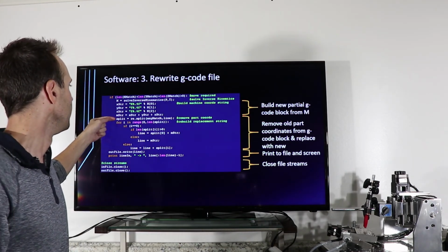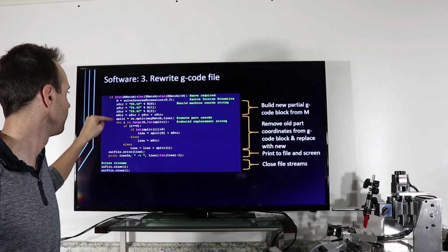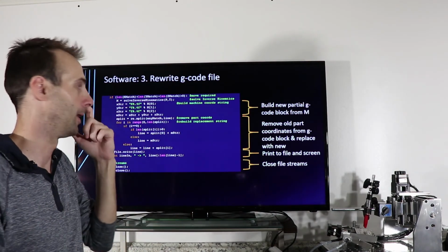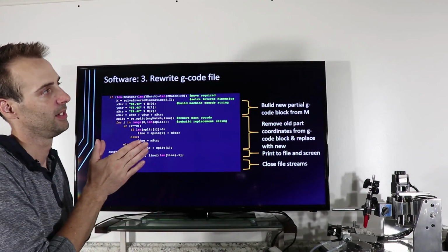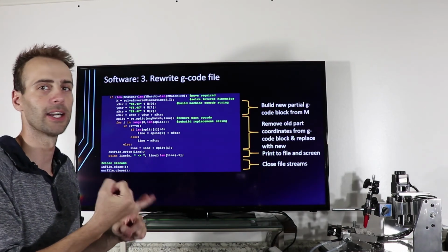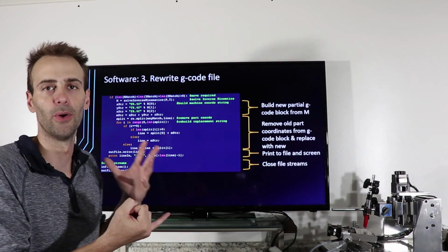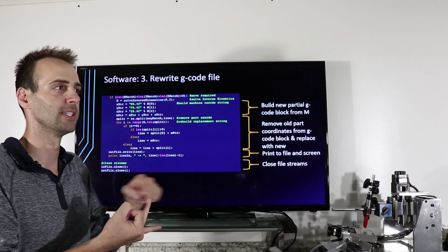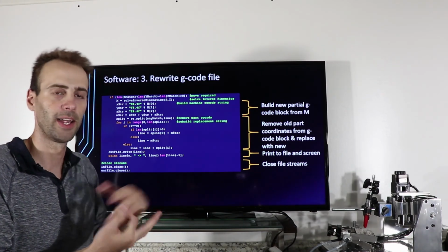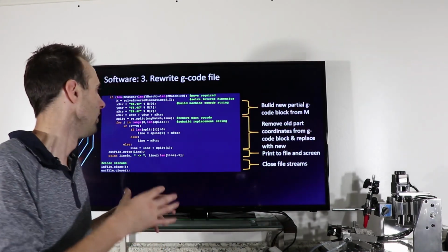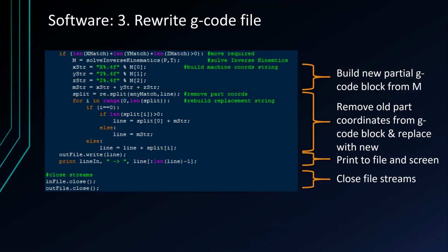and then we basically concatenate those strings, okay. Then this split function here returns an array of any match that's in there, and what it does is it removes it. So say there's an X, Y, Z move in there, it'll take the beginning of the block, say like G01 or G00, and put that as the first array element, and then the X decimal as the second element in the array, Y, Z, and then finally anything behind it, like spindle, whatever.